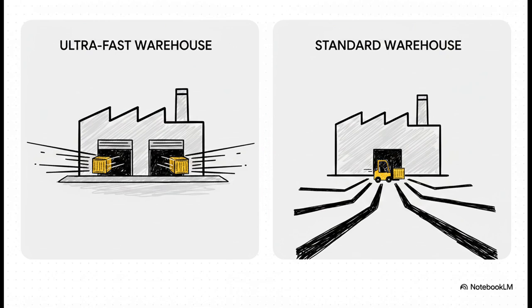On the right, we have single access RAM, or SARAM. SARAM offers way greater flexibility because it can be mapped to both program and data space at the same time. But it comes at the cost of speed. Multiple accesses here require one full cycle per operation.